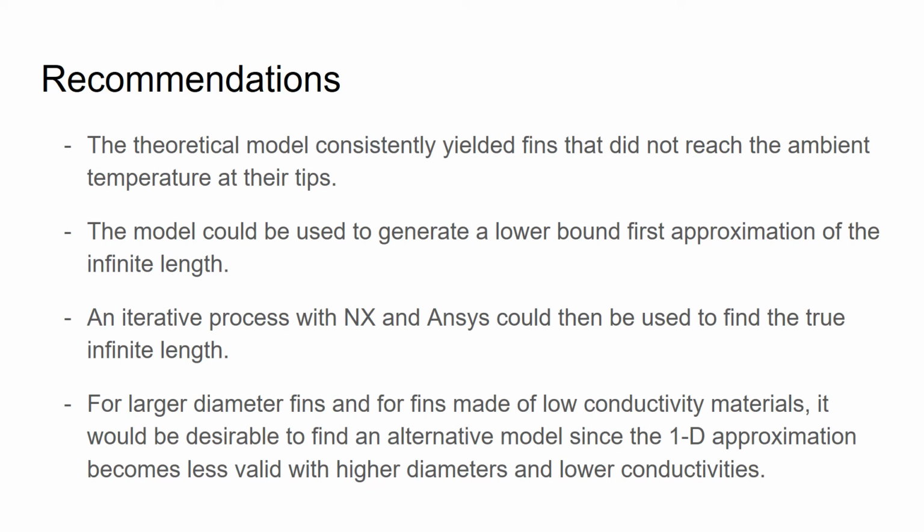The team finds that the theoretical model consistently yielded fins that did not reach the ambient temperature at their tips. However, this model could be used to generate a lower bound first approximation of the infinite length. From there, an iterative process with NX and ANSYS could be used to find the true infinite length.